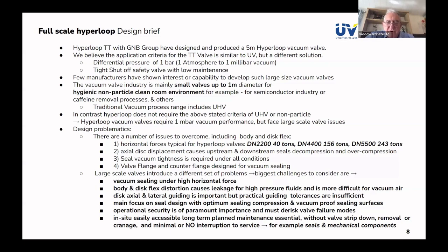So our main focus in designing this valve has been really the attributes of seal design and to achieve an optimum sealing compression, both upstream and downstream, to vacuum-proof sealing surfaces. And that's the surface of the rubber itself, as well as the mating disc, which has to be polished to a very high degree, because otherwise vacuum will pass.